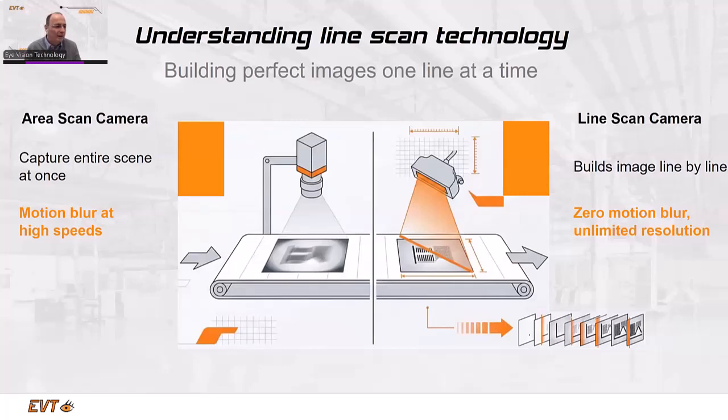If you only look at one line, you see only a very thin gray or color line, which doesn't give you a real view as a human of what you want to operate. But finally, the algorithms normally work on multiple lines, so that with multiple lines it also looks like a complete image for the human, and you can operate on these image fractions as you operate on 2D cameras, but with the advantage that lighting and lens are much easier to handle.